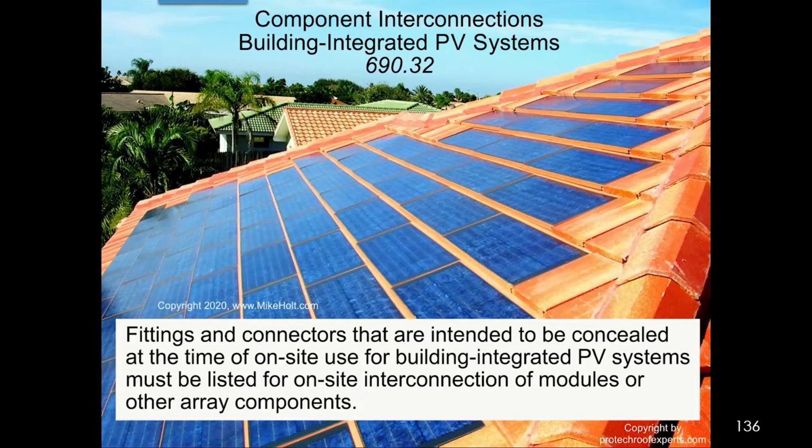Unless you can find ground readily available to you, you're still not at risk. So building integrated systems, as Brian is showing us, don't need to have a rapid shutdown system. Well, that one in particular would, but let's use a more current example. A lot of folks like to talk about the Tesla Power Roof, which is actually a glass module, so it doesn't have any conductive parts. And there are other companies, CertainTeed has a product, that have non-metallic products.